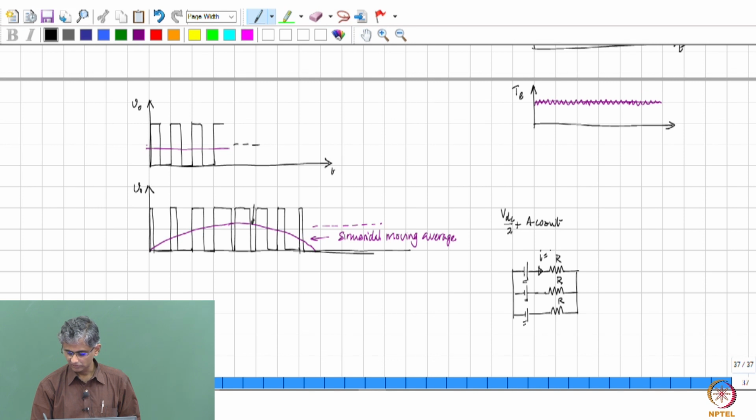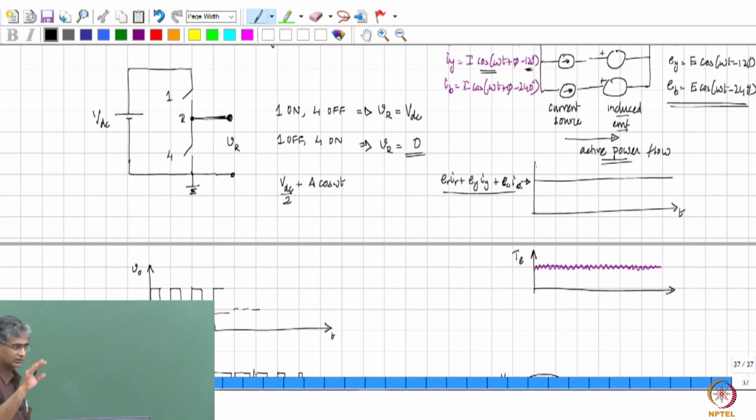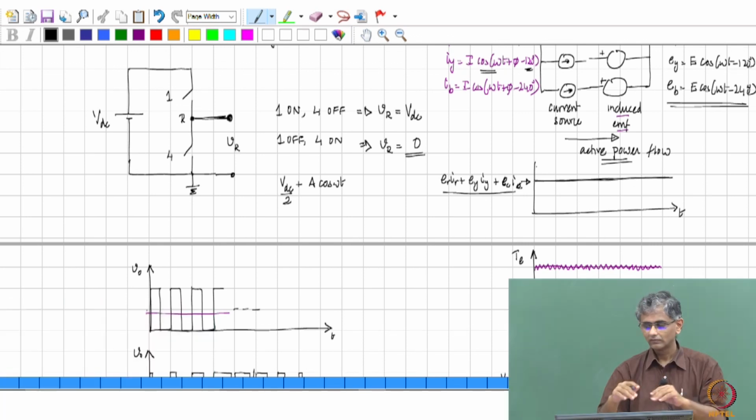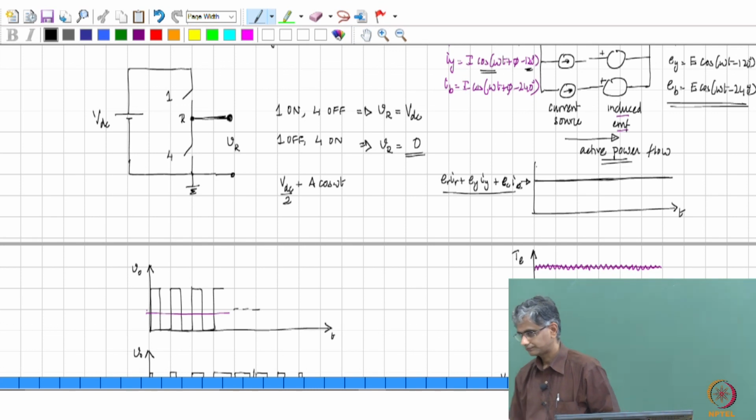Zero current will flow. And therefore, even though we are generating DC voltages here, since the DC is the same on all 3 phases, it will not pass a DC current into the circuit, into the motor. What will flow is only a current due to this excitation, and therefore we achieve our goal of creating constant active power with that switching up.